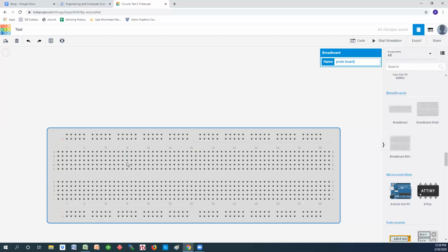The pins are the right size at 0.1 inch to accept all that. And also they're designed so the gates that come in what we call chips, they come in a dual inline package, which means there are basically two long rows of pins on them. It allows them to be placed in there very nicely.